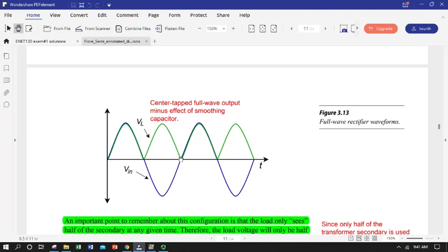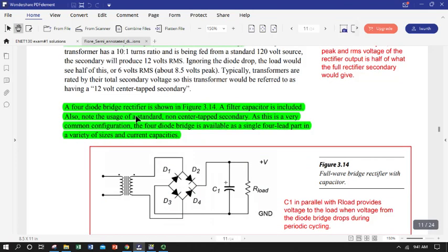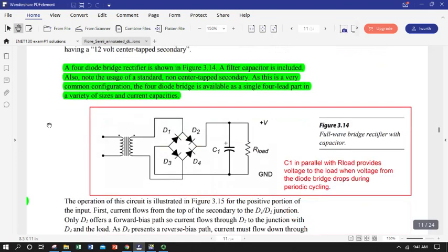So that's important to remember if we're going to do any frequency dependent processing or power calculations using our vector algebra that we used in AC. We've had a frequency change, so we don't want to go mixing up our transformer secondary signal and trying to apply Pythagorean or those other algebraic manipulations to the green curve, because the frequencies aren't the same. And there are other ways to deal with that we learned in AC.